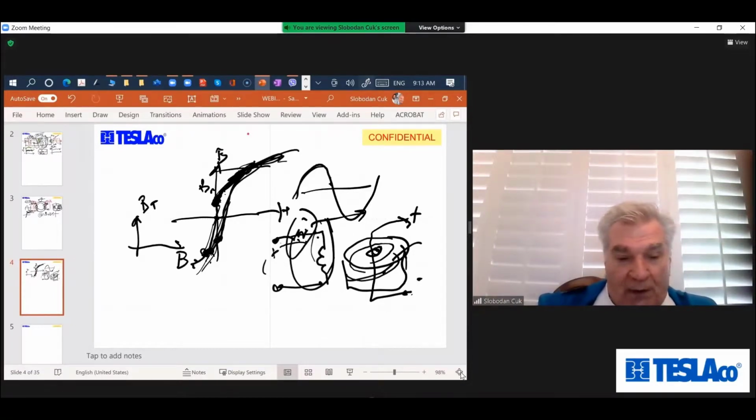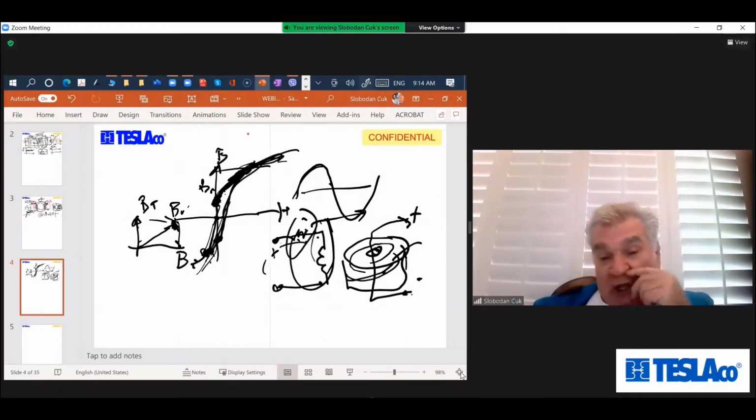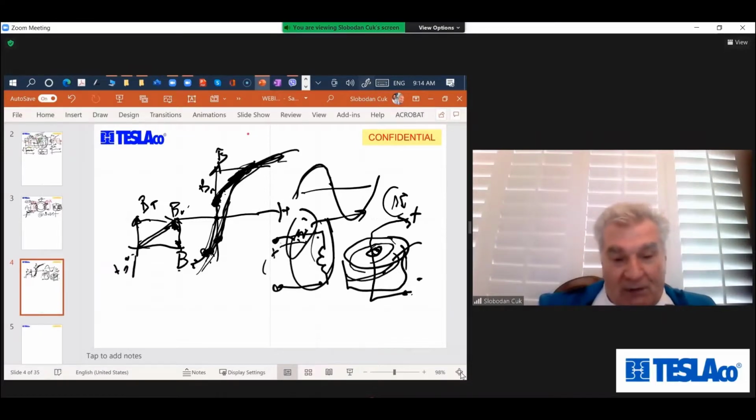And I was hoping, actually the reason why I suggested it, is that we could have a resultant flux which is one which saturates the core, so we could actually cheat and have 70% of the possible flux dedicated to the transformer and 70% dedicated to the inductor, and cheat to have both inductor and transformer using the same core with a maximum flux density of 1 Tesla, but each one having 0.707 Tesla in each direction, getting more done with less.